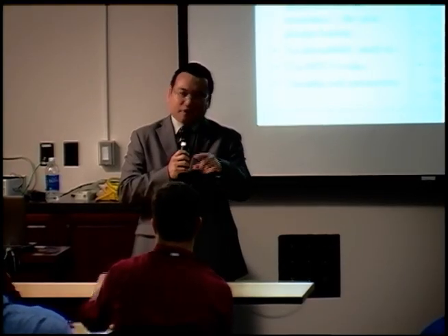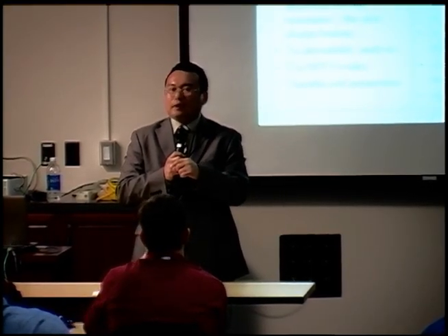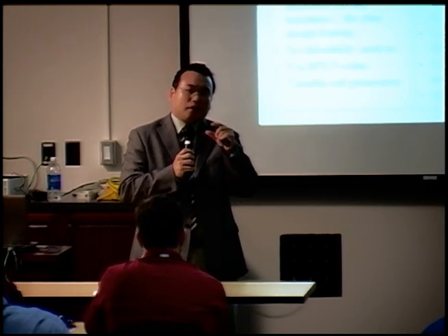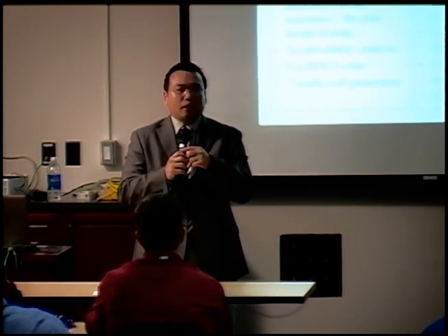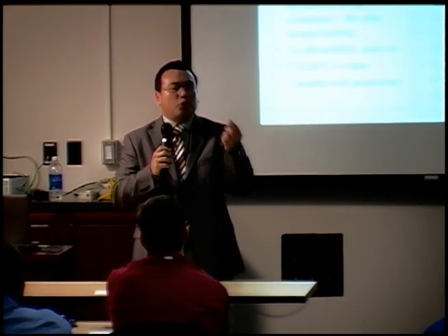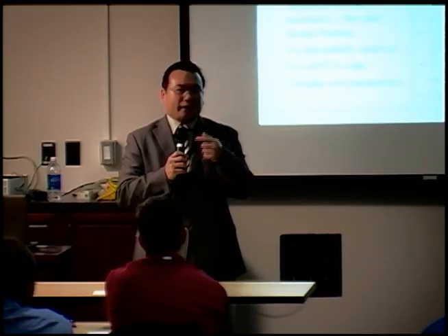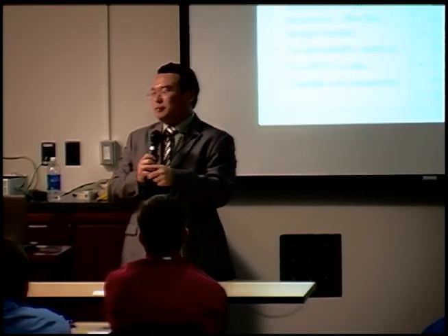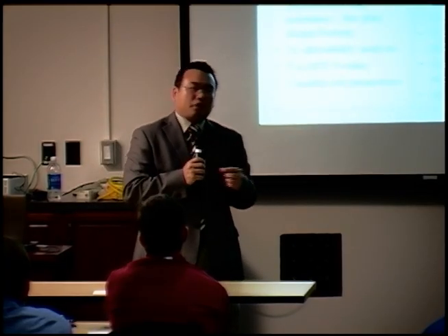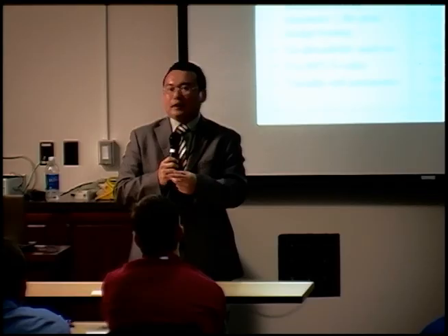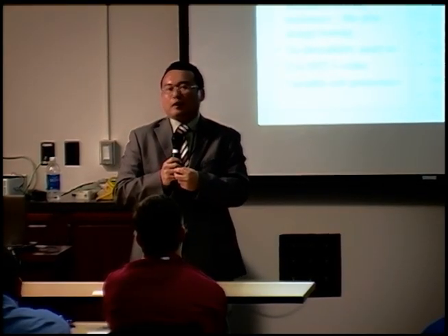But the benefit is that with the setup, you could reduce the chances of retapping the pile if you could not achieve that capacity at the end of driving. We'll talk about that in the afternoon. Right? But still, piles will be driven to the contract length. That is part of the policy. I think the DOT is still maintaining that policy.